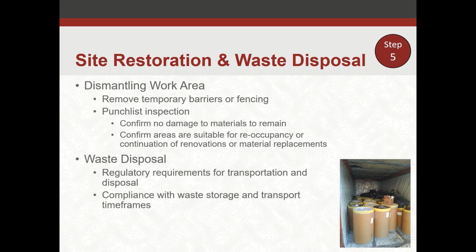As a universal waste, you have up to a year to transport that waste. A lot of times at the end of the project, you probably don't want to wait a year to get it out of there. The contractor is going to want to get their payment, so hopefully it's done a lot more expeditiously than that. But there are those requirements you have to comply with. And then some other things, like petroleum contaminated soil. A lot of times you're looking at a 90-day period for that because it is considered a solid waste. So try to get that out as quickly as you can, but definitely don't straggle on too long.